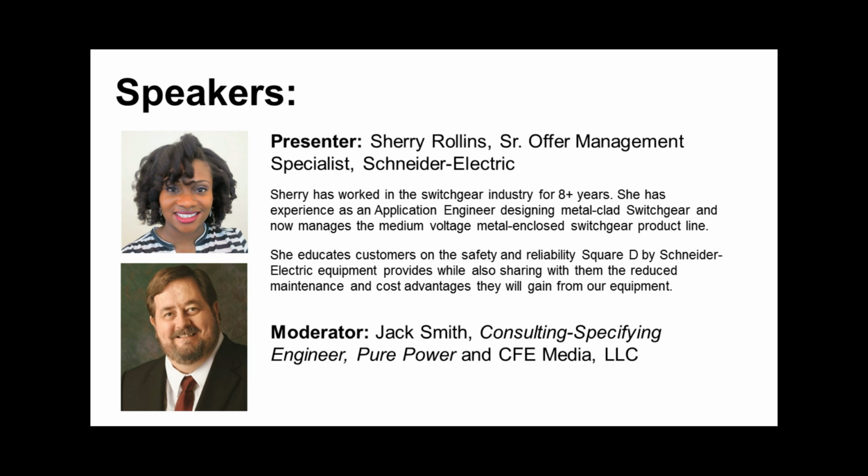So there's no reason why not. And I kind of mentioned this earlier. The criteria one has to consider is your existing cabling infrastructure and the consideration of how you're going to make those medium voltage connections to that existing switchgear. But you're going to have that same criteria whether you're fixed or withdrawable. But yes, there's absolutely no reason why one could not commingle the different architectures if one had the need to, for sure.